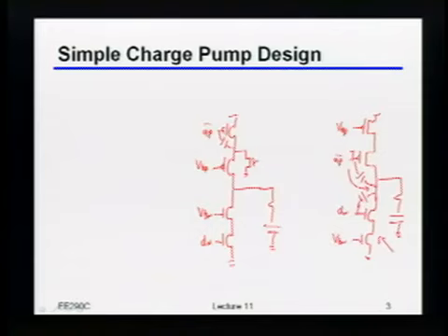Now, this is not entirely for free, because if you do this, you just have to make sure that the charge pump output voltage over here never gets close to VBP, or really never too much higher than VBP, because if it does, then obviously the switch turns over and bad things happen, right? But as long as you have a reasonably small range at the output, which we'll come back to in 1 second, then you could try and play some game like this.